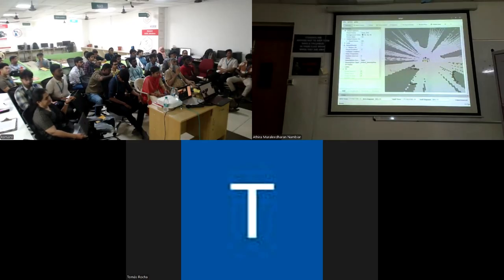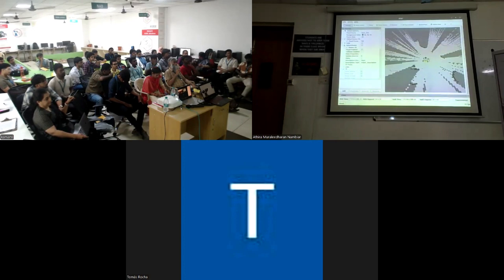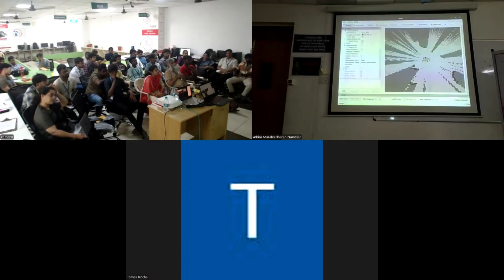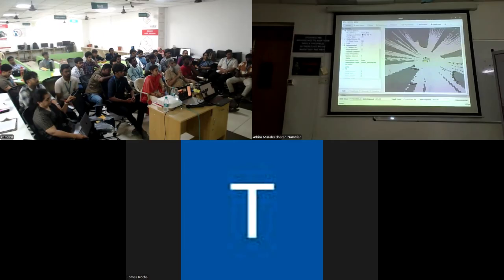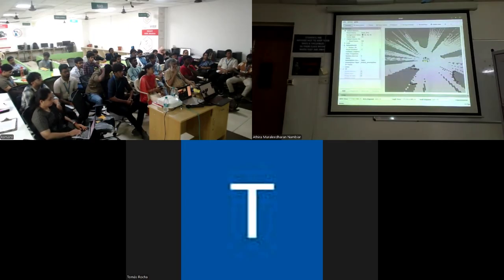We are using Hector SLAM, a very simple model, which is quite easy for devising the path planning. You have multiple SLAM algorithms, but we are not going for a complex environment. We are taking a limited sequence because we don't want to put heavy complexity on the path planning, so we are reducing the path planning side and then deploying it.